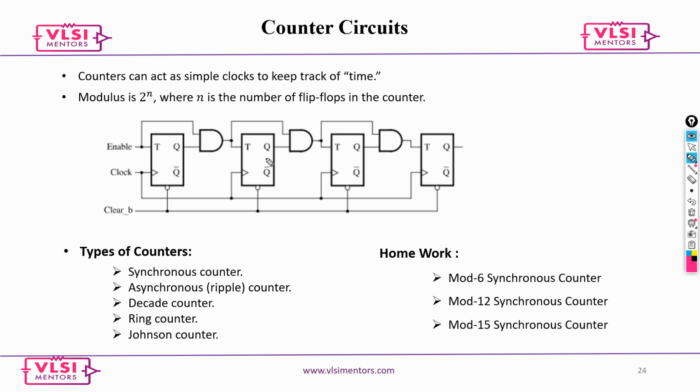Because look at here, what type of cell it is. Okay, it is an AND gate. Now what is the delay that it is going to take? Say this is A, this is B, say this is Z. What is the delay it is going to take when the signal at A changes, A to Z? And when the signal at B changes, B to Z, what is the delay it is going to take?